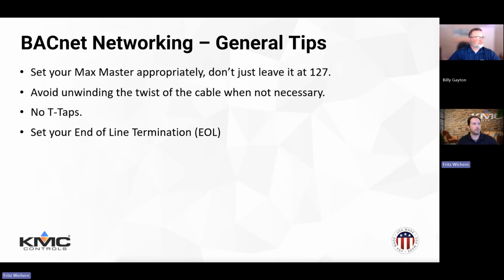Sorry, my points are coming in all over the place here. Let's start at the top. Set your max master. That's a big one. No, it doesn't always seem like it's that big a deal, especially when you're dealing with maybe a small network, but it can make a difference. So go ahead and set it. You can leave a few past it in case you ever add devices. You've got room and you don't have to change them. But if you do have just 20 devices on that network, it's going to keep looking all the way up to 127 if you don't set that max master.